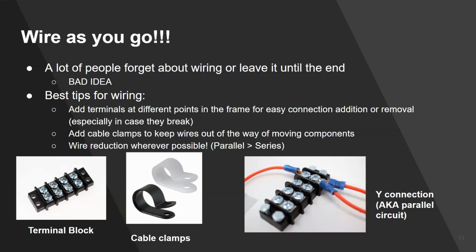I used to pile on a few to make sure that, okay, now I have all of my positive wires going directly to this one. Perfect. This is a positive wire. Good. That's all it needed to be labeled. And then it's a positive wire leading to, let's say this one's for my wheels, this one's for my claw. Perfect. So I'd write claw here and then wheel there. And then over here, I'd write claw and wheel, going all the way to the next part of it, claw and wheel. And I know what's controlling what, and you're reducing the amount of wires going through your robot.